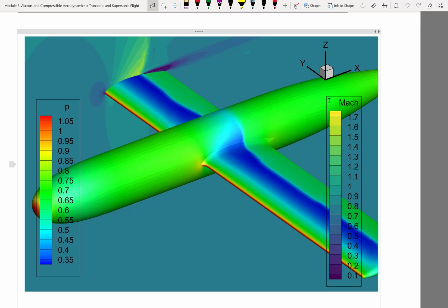And in the shock wave, of course, mass is still conserved. Okay, momentum is still conserved. Energy is conserved, but there is a lot of mechanical energy transferring to thermal energy. Okay, so if you look at the wake of a transonic aircraft, you can actually spot the area of the air that has passed through a shock wave by a heat signature.